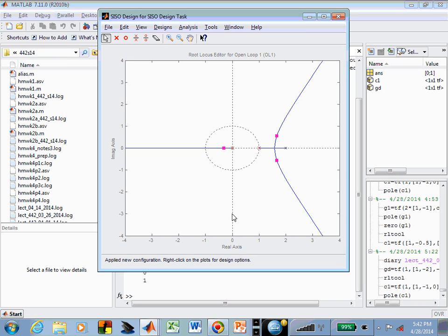So all we've done so far is we started with a pole at z equal 2. We've now introduced a pole at the origin and another pole at z equal to 1. And that's the root locus that we would have to sketch if somebody said, oh, you have a 3-pole system, right? We haven't yet introduced the 2 zeros that we have the flexibility to select in our PID controller. Does that look consistent with a 3-pole system and no zeros?